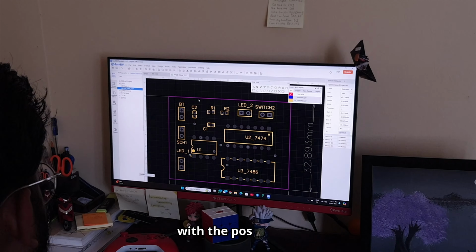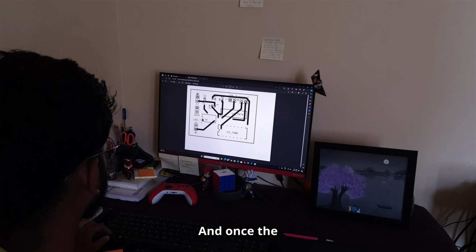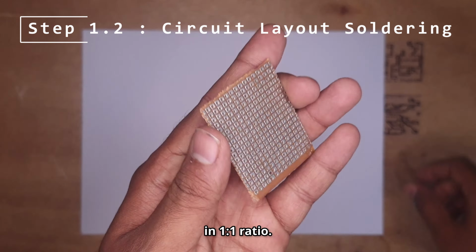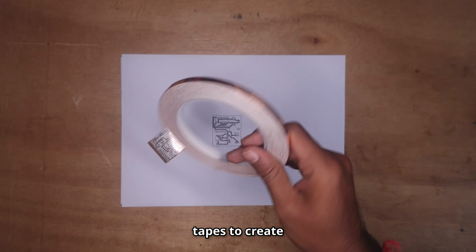We can play around with the positioning of the components and use the auto route feature to create a layout. And once the layout is done, I am exporting the same as a PDF, which then is taken as a printout in 1:1 ratio. Now, let's transfer the trace to the perf board. Here, I am using copper tapes to create the trace.